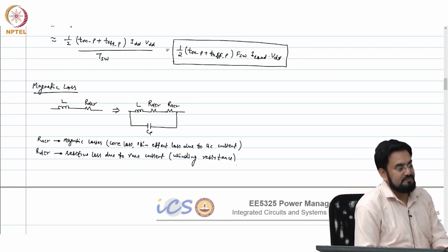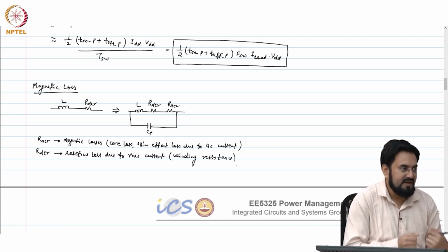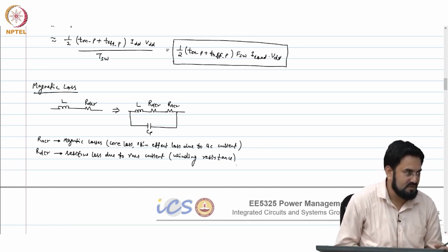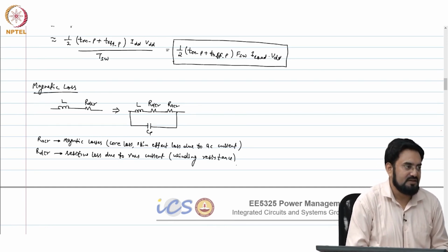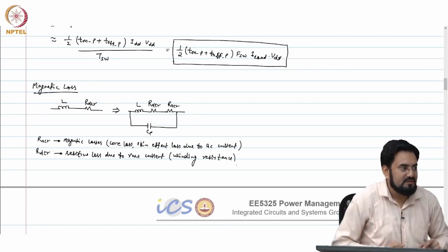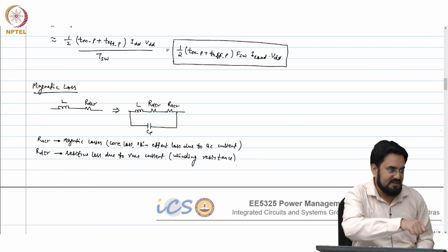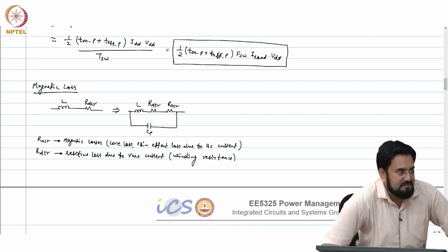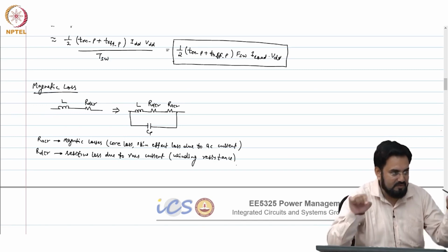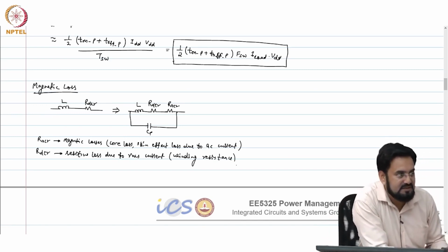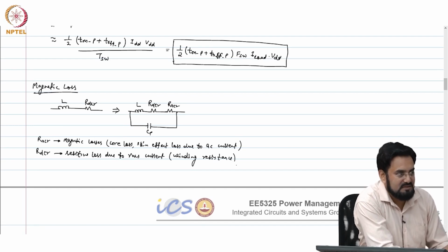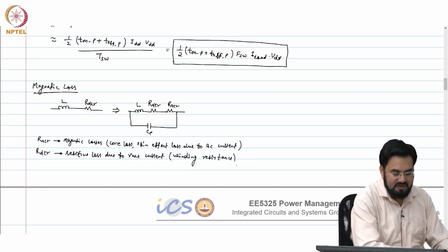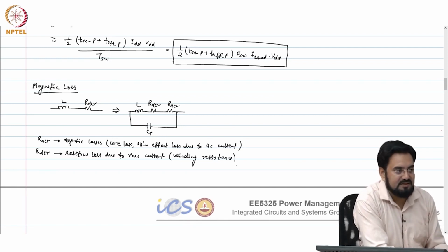So, these inductors have a coil, the windings, and that will have some finite resistance. So, that is what it represents. Measuring RDCR is very easy. You can simply use the ohm meter. Use your multimeter, set on ohm, and apply your probes across the two terminals and you will see RDCR. Or you insert some DC current and look at the voltage drop across that. So, IR drop will also tell you the resistance, but RACR is not simple.